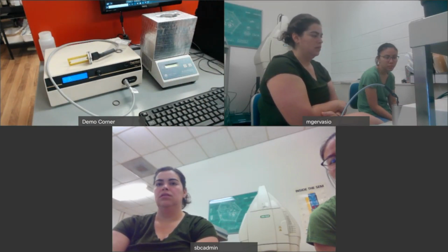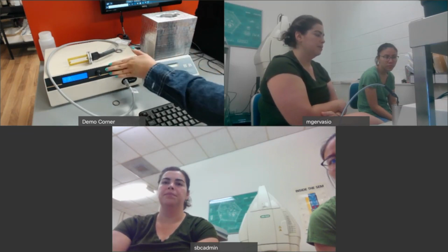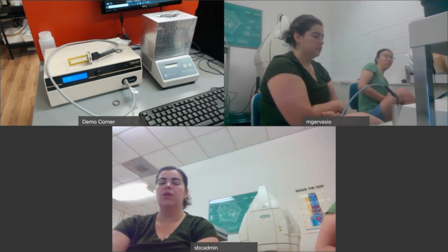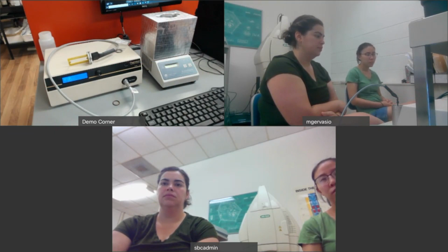Yeah, and we suggest if you just want to see how the measurement is, you can use the front button. I'm not suggesting to use it for the calibration of the sensor because they are not using the same formula, not the same algorithm. The front button uses a constant power for all fluids, but the detect power adjusts the power according to the fluid you are measuring. So the most accurate results are through the software.